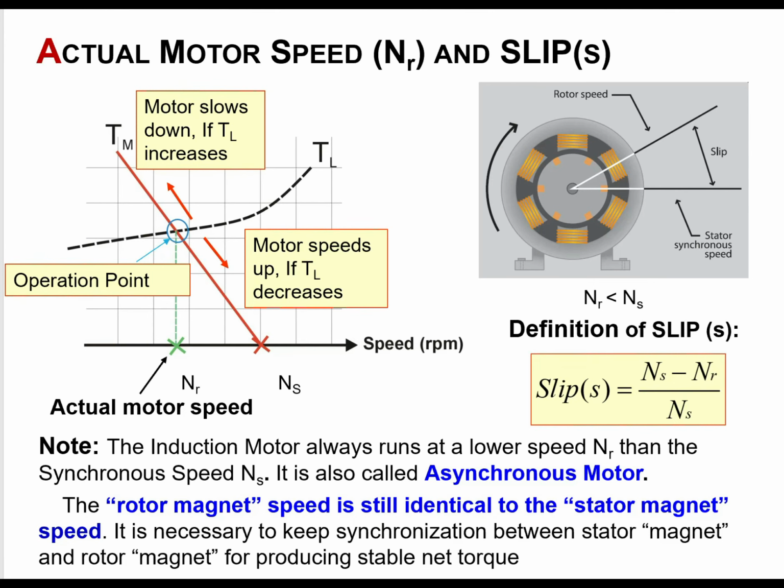Now notice that the curve in red is for a motor driving a load, which has a load torque curve shown in black. Now the motor is working at this operation point. So over here is the operation point at a specific speed. Any disturbance to the motor system causes a reduction in the speed. And at lower speeds, the motor torque is greater than the load torque. Consequently, the motor will accelerate and the operation will be restored to the operation point.